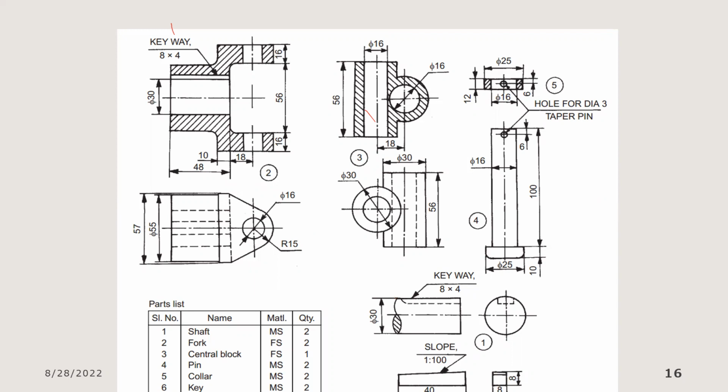So we are still at the examination stage. We've looked at all the parts and the quantities we have. Then you also choose a proper scale. We assume all that is done. Number 4, estimate the overall dimensions of the views. We assume that is done. Then you draw the axis of symmetry for all the views of the assembly drawing. Okay, we'll be getting to that in a bit.